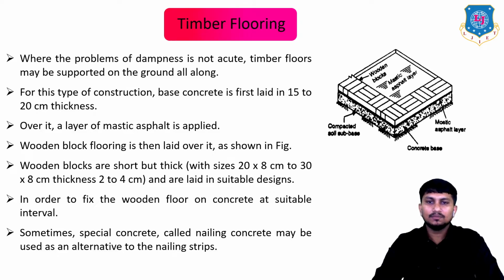And these wooden blocks are laid in suitable designs. In order to fix the wooden floor on concrete at suitable interval, sometimes special concrete called nailing concrete may be used as an alternative to the nailing strips. So this is how you can construct the solid type of timber flooring where dampness is not the main problem.